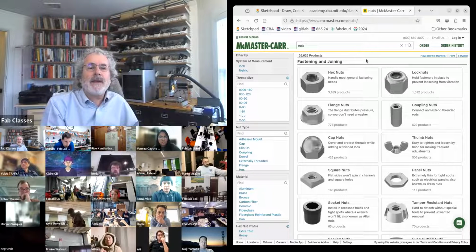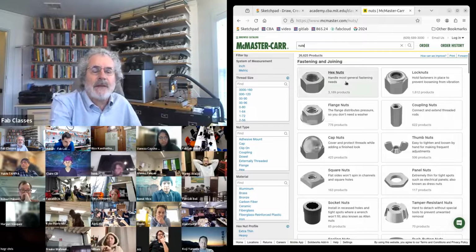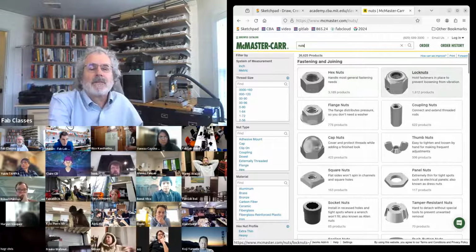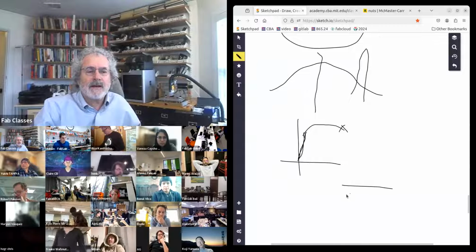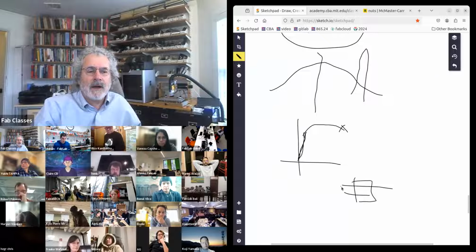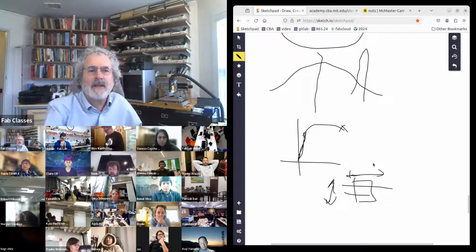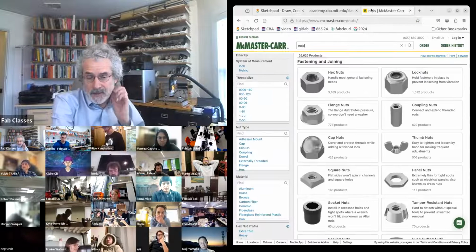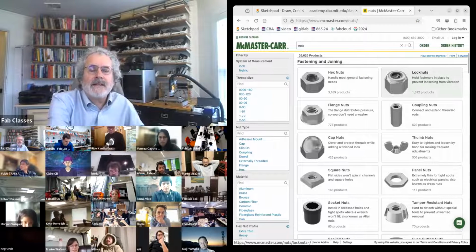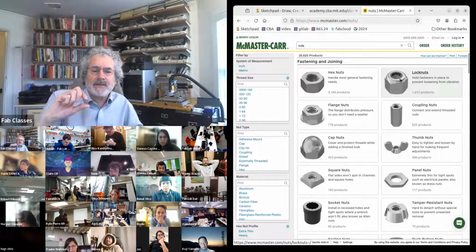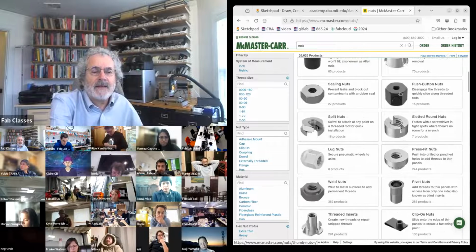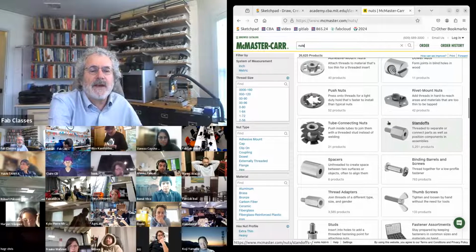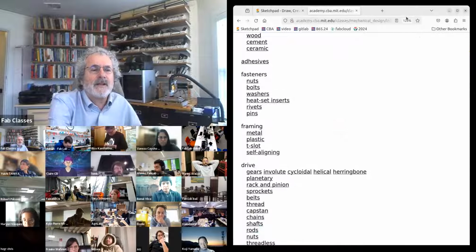So the humble nut, there are many kinds of nuts that we use. So there's a basic nut you screw on. When you have a machine with a threaded rod and a nut, the machine is going to vibrate, and that'll make the nut walk, which is bad. And so lock nuts have a little elastic deformation. And so when you tighten the nut, the deformation helps keep it in place. And then a little bit, I'll talk about more advanced nuts that are anti-backlash nuts that are spring-loaded to prevent hysteresis.